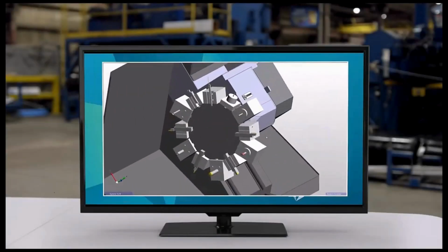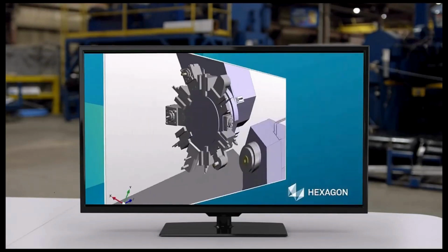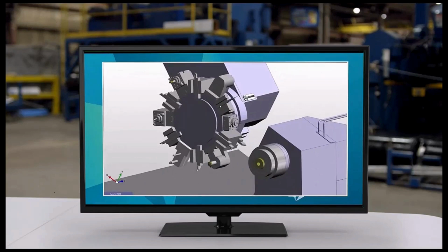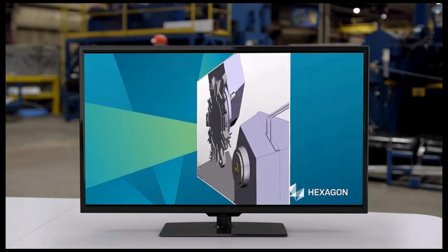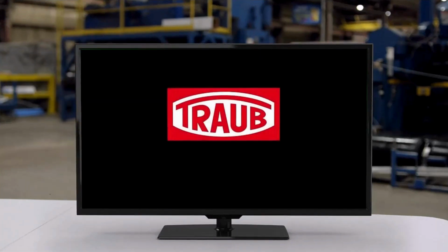This snapshot from EDGECAM Simulator shows a lathe turret with turning, drilling, boring, and live tools. This snapshot now has shared tools in those stations on a twin spindle type machine. Today we're going to be talking about the tool mounting blocks that hold these tools to the turret.